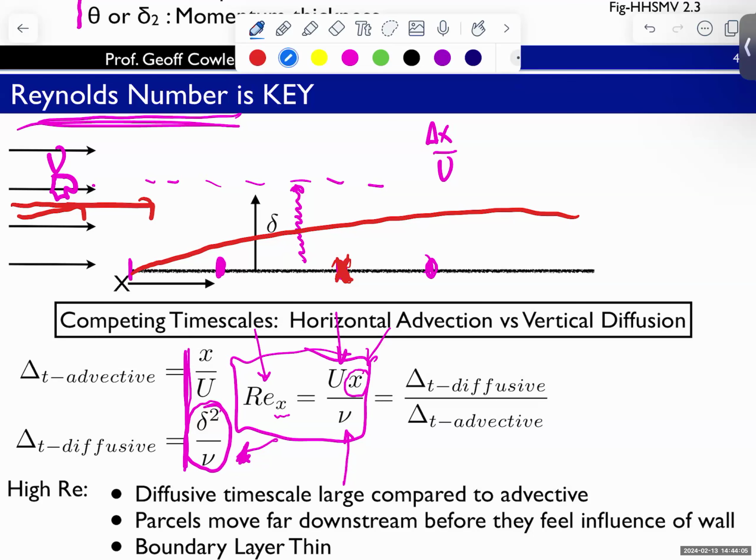And we'll see the impact on the boundary layer is twofold. One is that we'll see a change in the skin friction. We're going to quantify that later. We'll see the skin friction coefficient will change. And the other is that we'll see the boundary layer will become thinner. And this is a little non-intuitive. People think about higher Reynolds number, why wouldn't the boundary layer be thicker? Well, in fact, it's the opposite.